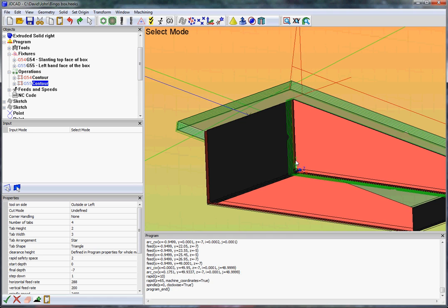The idea is that the fixture is a coordinate system which gives you the starting point, 0, 0 coordinate, as well as the plane of where the x and y axis are, what plane it is on, where it all starts. And that describes it in terms of the graphics file, but it also describes it in terms of the G54 or G55 coordinate systems on the CNC milling machine itself.